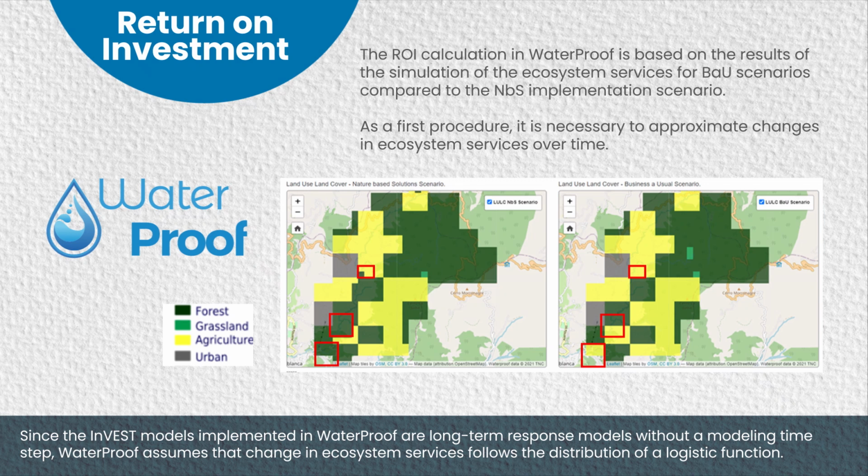because Waterproof estimates the concentrations of sediment, nitrogen, and phosphorus in the water body at the water intake point. This is to estimate the water quality characteristics at the water source. Then Waterproof with its algorithm generates a raster of land uses considering the effect of change in coverage expected by the implementation of the nature-based solutions.